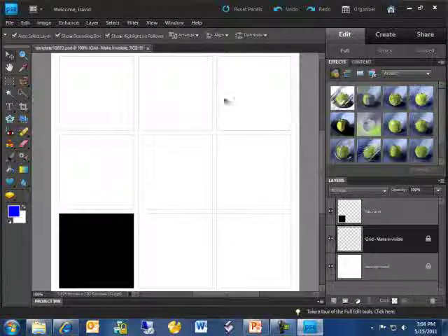Okay, so now what we have around here is the template background, and over here on the right hand side is the layers palette. Hopefully you had a chance to read about that in your textbook. We have the basic 2-unit square, and as we work with additional design templates you'll have more building blocks here to work with. And then we have a background layer which gives us this white area here, and then we have the grid layer which is the fine gray lines here. And the visibility icons mean we can turn off or on visibility. They're all visible. The eyeballs are all there.